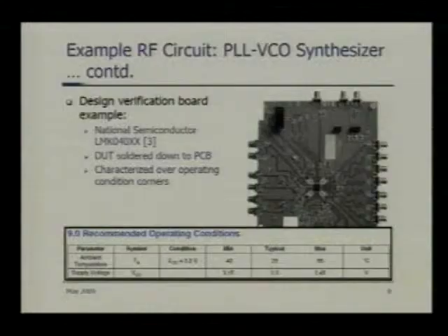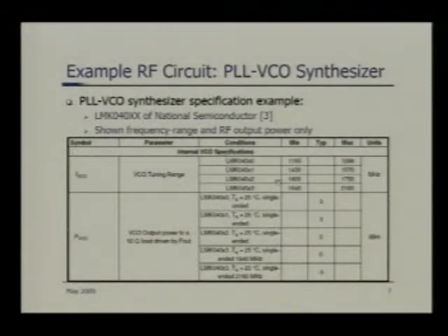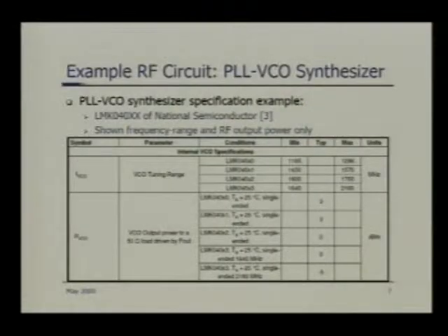So here I have, say, 0 dBm, and let's say the uncertainty is about 0.2 dBm. Now if my acceptance criteria is 1 dBm, and in the production test I measure an actual RF output performance specification of 0.9 dBm, we know that there is plus or minus 0.2 dBm uncertainty. So we really cannot use the 1 dBm as the acceptance criteria.